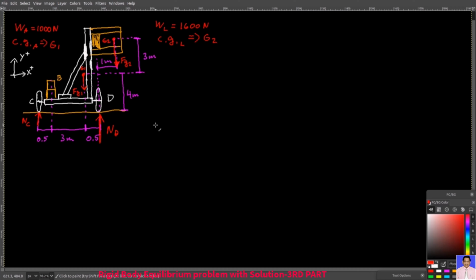Now, of course, you might argue that there should also be reaction forces in the x direction, because due to friction, wheels normally don't go sideways. However, you cannot count on it. It depends on the wheels and the surface. What if you are on the ice? Then it would be easy to slide the structure laterally in the x direction. So it's simply better to assume no friction at all and design the whole thing without horizontal reaction forces, just to be safe.